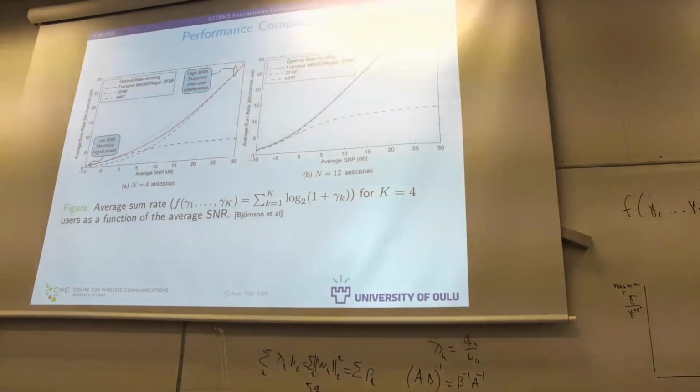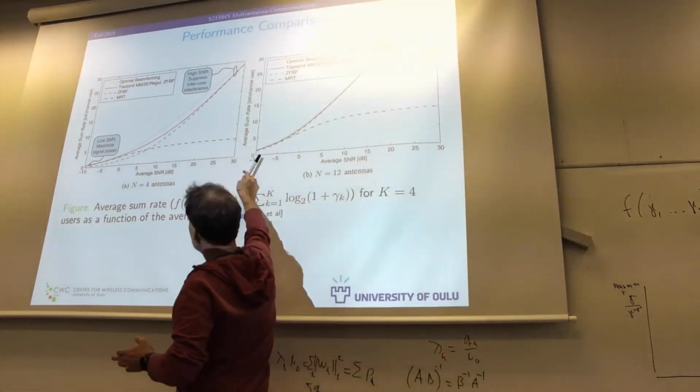Maximize the minimum rate, and obviously, since we have this bijective mapping, it's equivalent to maximize max min gamma, right? Because in the end, the rate will be the same for all users. The SINR will be the same, so it's the same. Maximizing the common SINR is the same as maximizing the common rate. Okay? And this is what you are asked to do.